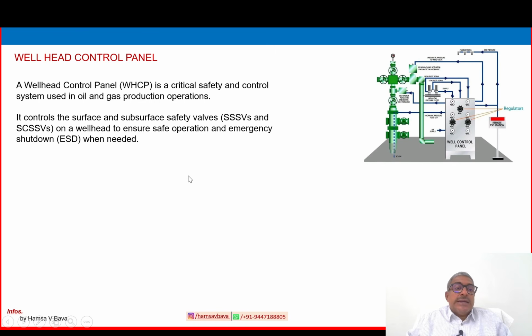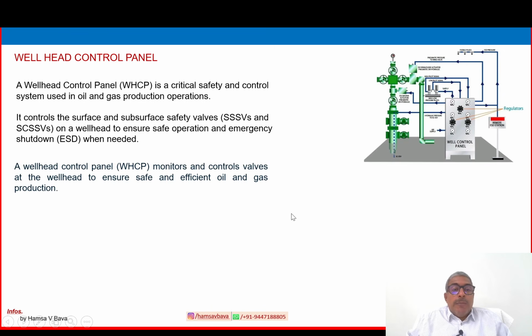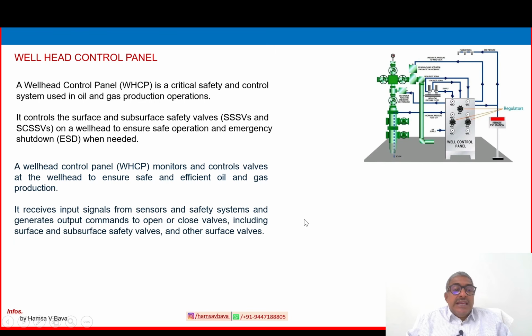So it controls the surface safety valve and subsurface safety valves and ensures safe operation and emergency shutdown whenever required. A wellhead control panel monitors and controls valves at the wellhead to ensure safe and efficient oil and gas production. It receives input signals from various sensors like pressure transmitter, temperature transmitter, flow transmitter, or fusible plug.